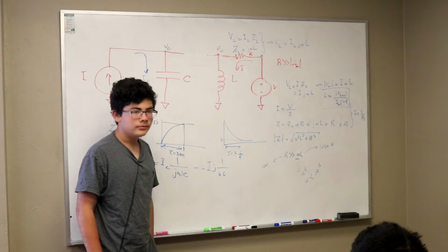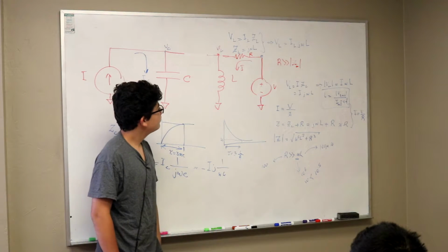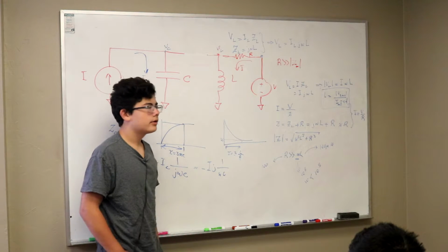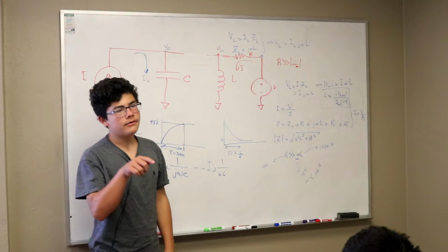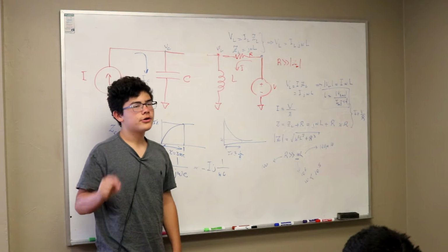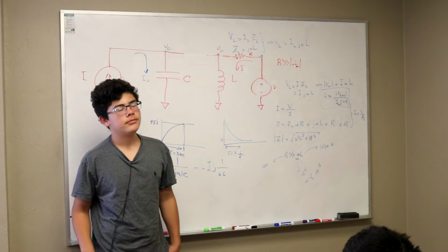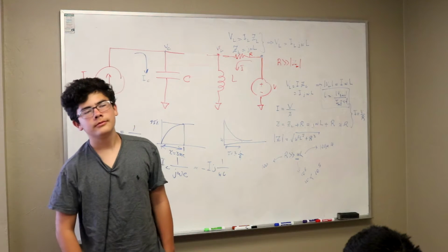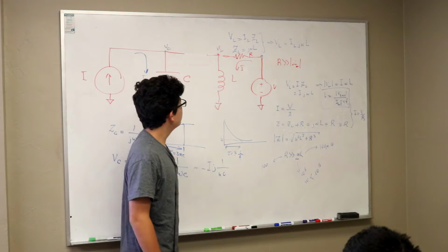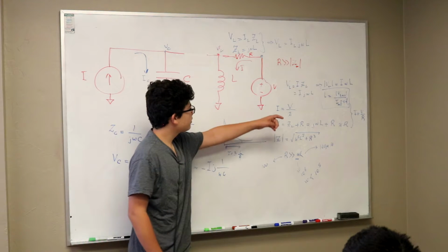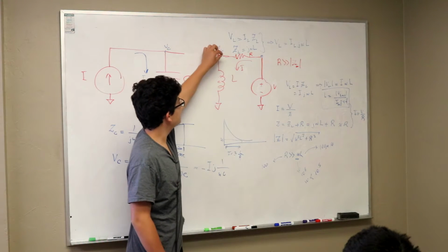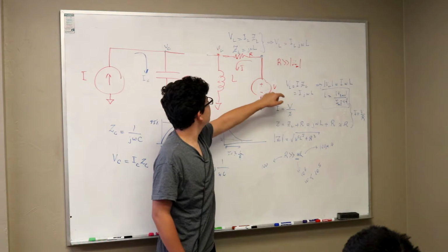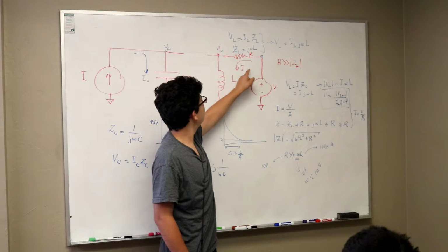And where do we measure? So how are we going to measure the I max? On the oscilloscope, get the math function or the cursors, and then put it on the top. Exactly. So where are you putting your two probes? For VL max, probably right here, and then for I max, probably.